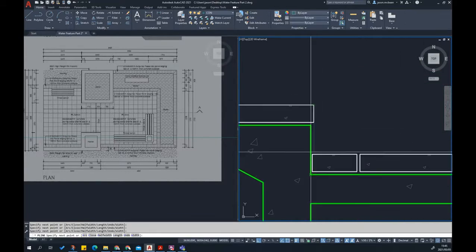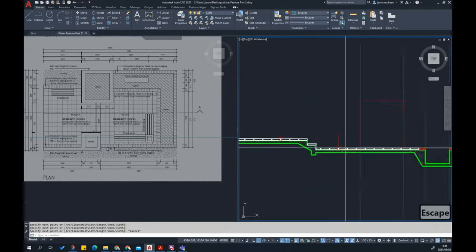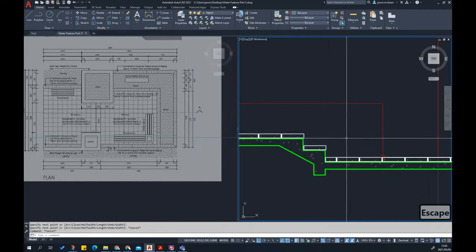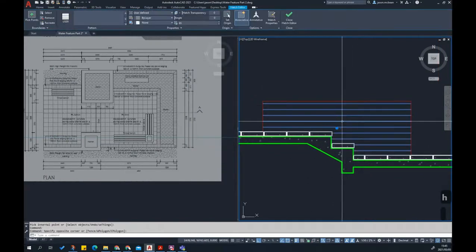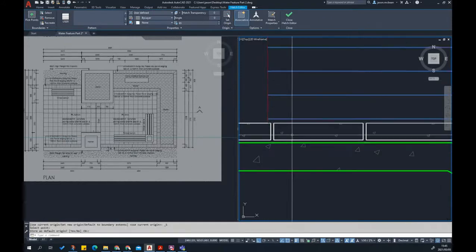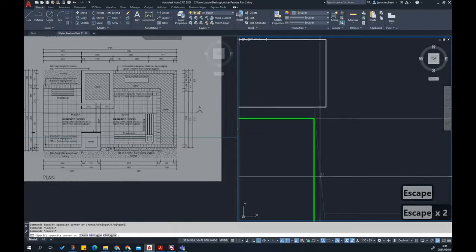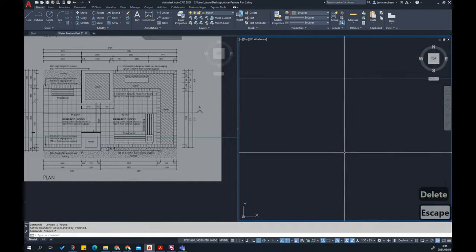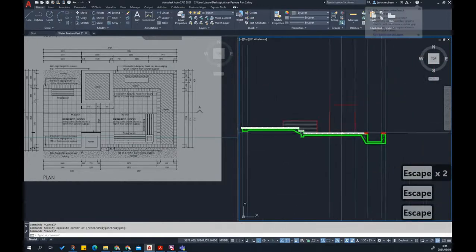But like what I'm doing, this would be fine. So I'm just going from there to there. I'm just closing it off. Now if I go to hatch, just make sure the hatch layer is activated. Hatch. Now if I go to hatch, it will hatch fine. Just remember, I need to change the origin. So set origin. I want this to be my origin over here. There we go. Okay, so it's changed my origin. So that's worked pretty well. And I can just get rid of this construction layer. Okay, that's kind of worked. It's done exactly what I want to do. This hatch, yes, doesn't have to go past. You can neaten that up, but in essence, it's done exactly what I wanted to do.